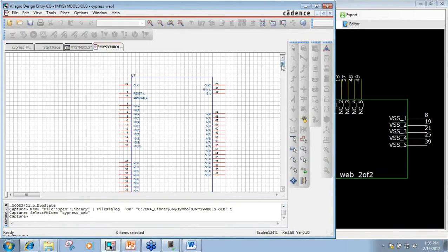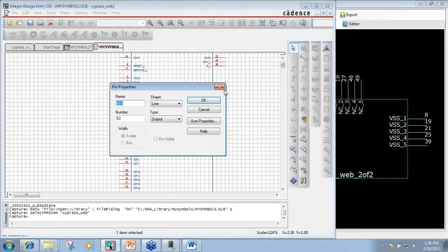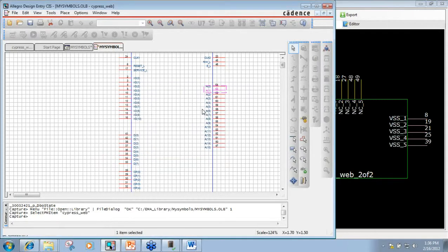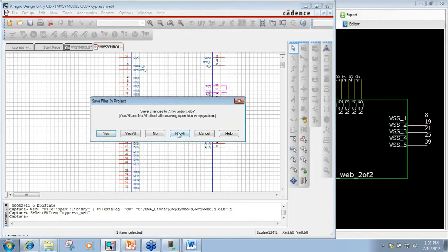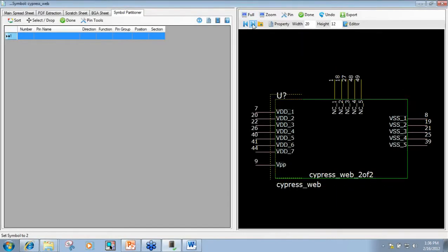This one, 64 pins. You notice that it did retain all the spacings that I put in my canvas in EDABuilder. We got the correct pin names, pin numbers. You know, all these pins have their unique properties. That all comes across. A couple of things that I didn't mention when I was building these parts is just some of those other editing capabilities that you would have.